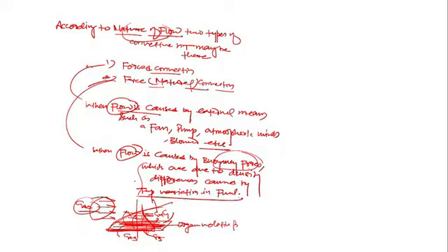Similarly, when mass transfer takes place from the surface of a solid, near the surface the mass transfer is by purely random motion of the molecules, meaning molecular diffusion, and that mass transfer by molecular diffusion will get swept away by the fluid molecules, because in the upper layers the fluid is in motion, and that causes the bulk motion as well. So the combined mode will come into the picture here.